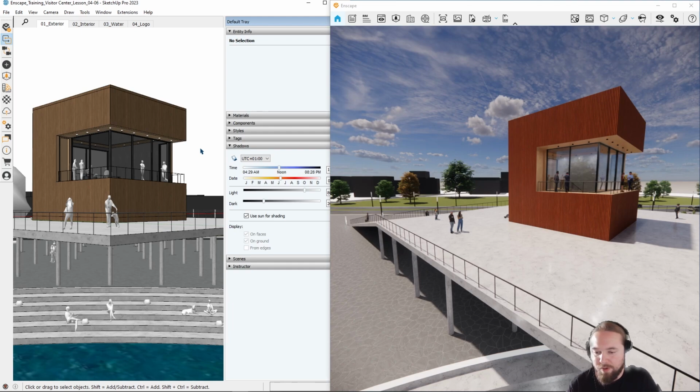In Revit, you can even combine things like design options and construction phases with your views and so on and so on. But let's take away that information for now. That is the principle of Enscape. If you do something in your host application, it is going to be reflected in Enscape right away, unless you have disabled this button here, the Live Updates button. If you uncheck this button in the top left corner, then your updates will no longer move over to Enscape until you enable this again, which helps if you have tons of small updates you want to perform.